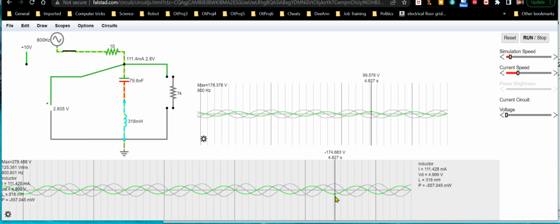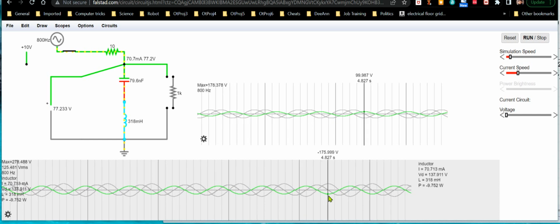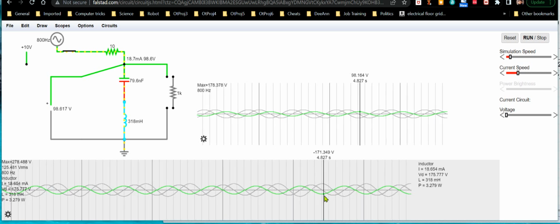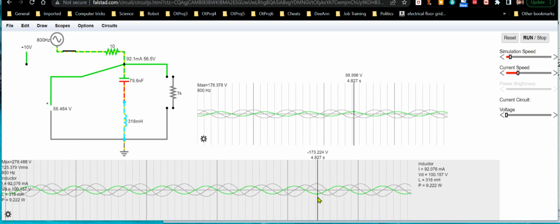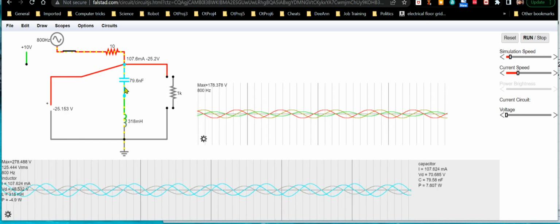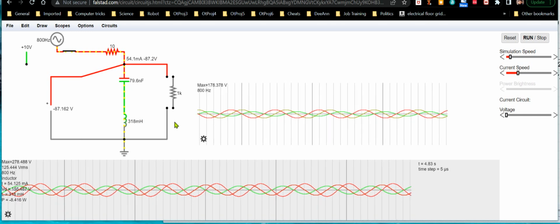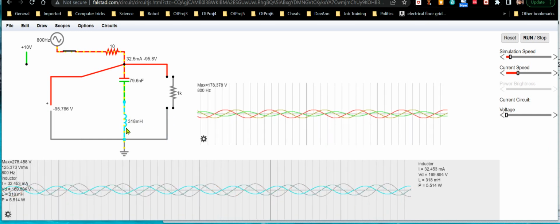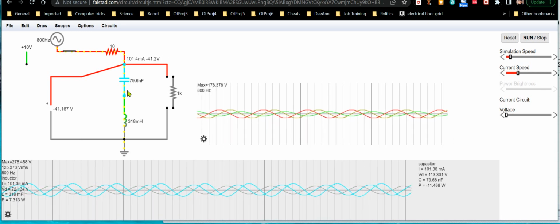But that's what I've always read and heard, that at resonance the voltage can get really high, and it can blow out your inductors and short circuit your capacitors if you're not careful and choose your components right. I was always interested in it as a way of generating high voltages, but just like I was talking about earlier in the video, you've got to make sure your capacitors and inductors are really high voltage rated to make that work. Otherwise you're going to be shorting the coils and blowing holes in your dielectrics and capacitors and everything else.